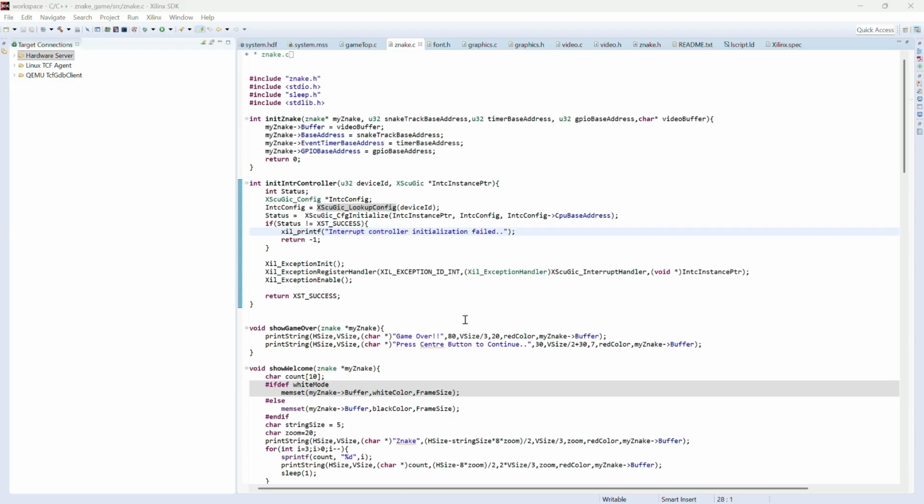The next issue I had is a relocation issue. Sometimes prey was generated inside the snake, and hardware moved it automatically, but it was not updated on the screen. How I solved this was I added logic to redraw prey after relocation, and this kept the hardware and display synchronized. After solving all these issues, the game ran smoothly. No glitches or freezing issues happened, special prey worked correctly, and hardware and software were fully synchronized. This project helped me to understand real-time embedded systems, hardware software co-design, and debugging complex synchronization issues.